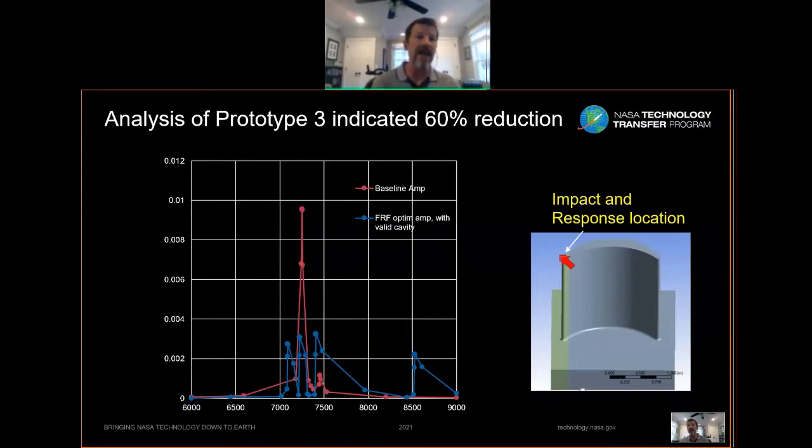As I mentioned, it's not efficiently excited by this loading. And so the goal is what happens here with your tuned mass absorber. You have 4 modes, but the peak response of each of those 4 modes is way below the original baseline. It's a 60% reduction, actually, in your resonant response, your peak response. So that's the goal. That's what you're trying to achieve.